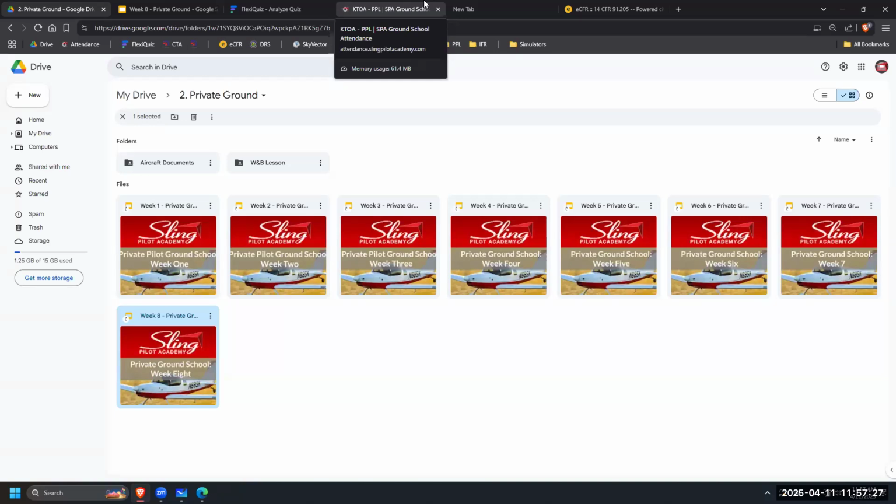You turn this one off and it's still smoky, smoky, smoky. And now the smoke goes away. Maybe it was the electrical fire. You turn this one off and you say, okay, this is solving the problem, and I don't have to turn my avionics off. What happens if you turn your avionics off? Yeah, I can't talk to anyone, right? Then I really have an emergency now. Not saying that this is a priority, but what does the checklist say? POH. Anybody got a POH in front of them? Electrical fire.